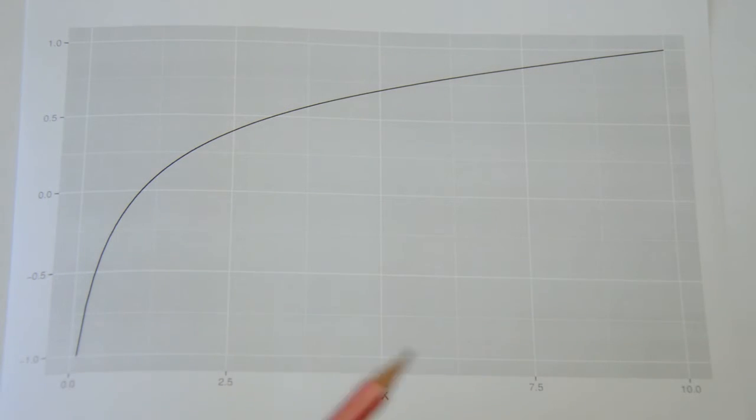At the same time, if we apply a strong signal, we have to move considerably more to the left or to the right to measure the same change. So that's a bit of a compromise. It's compressing the space of your input in such a way that you're sensitive to weak signals here due to the steep slope of the curve, while at the same time you're still able to measure changes of strong signals just in a less sensitive way.